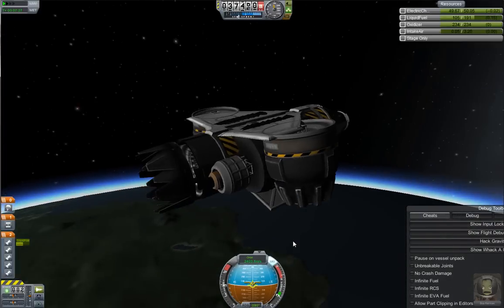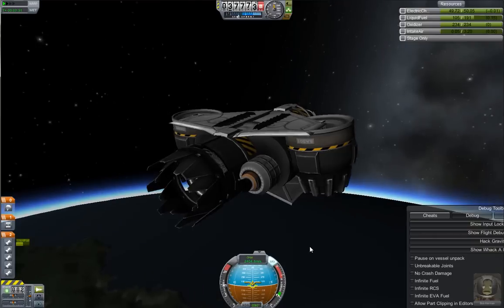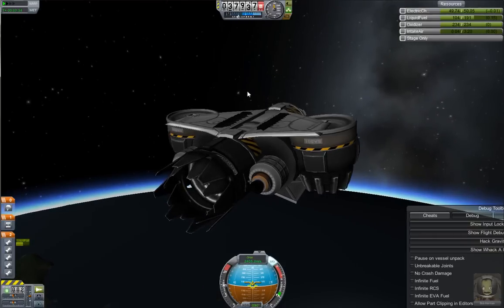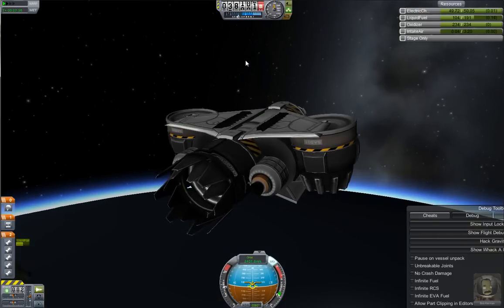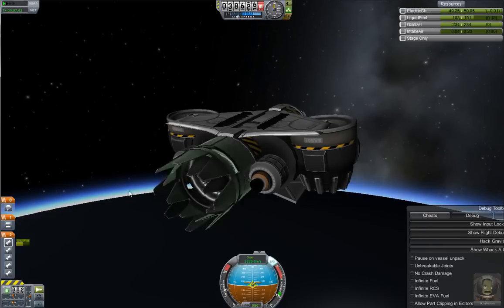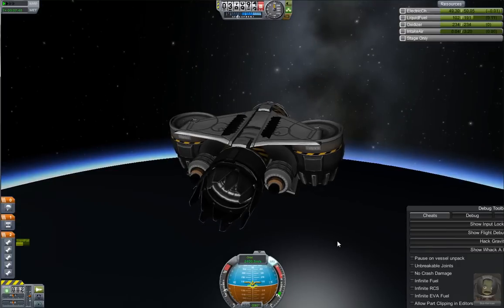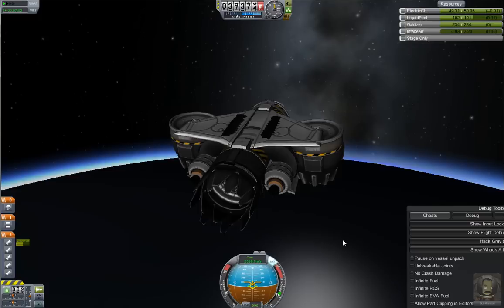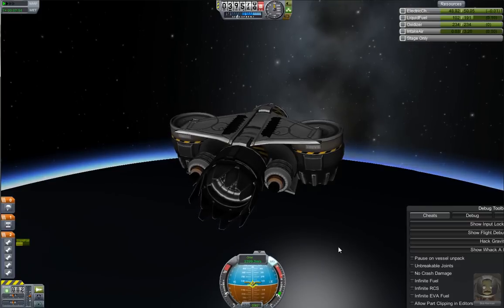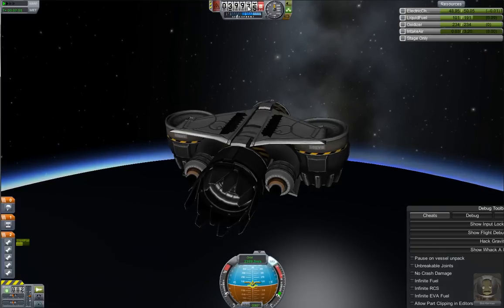If you haven't gained at least 2400 meters per second for orbital speed, you want to stay between 33,000 to 34,000 meters and try to get up to that speed before you attempt to slowly get altitude. Because what you're doing now is you're not really accelerating as much as you are just trying to hold that number for meters per second as high as possible.